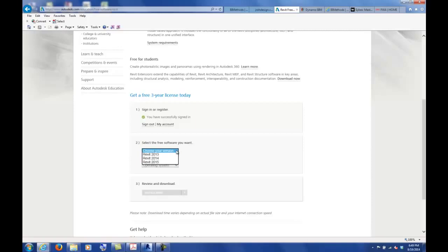especially so that you can also utilize your files with any of the software that's available on the school computers. One thing about Revit to keep in mind is kind of like InDesign. I don't know how familiar you are with InDesign, but essentially Revit 2015 can open any file from Revit 2008 and on. However, if you're in Revit 2014, you can't open Revit 2015, and once you open something in Revit 2015 and it upgrades, you can never downgrade it again.